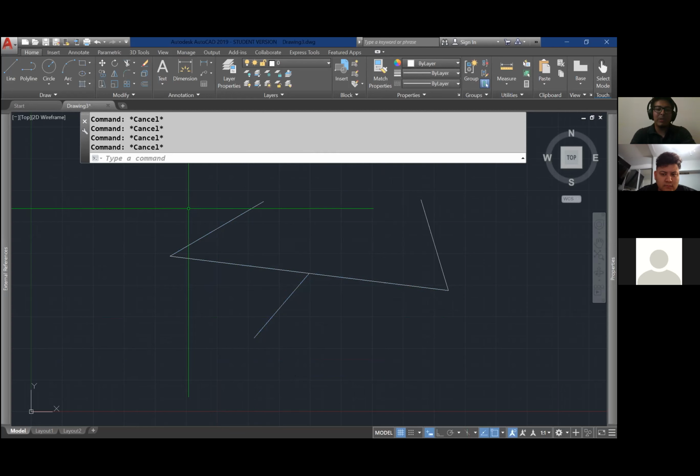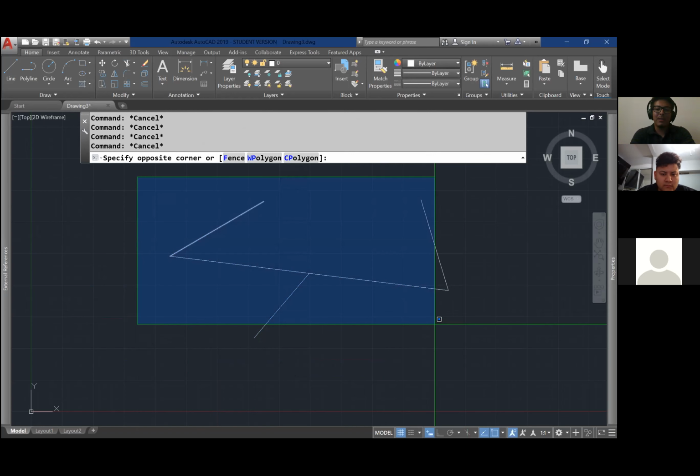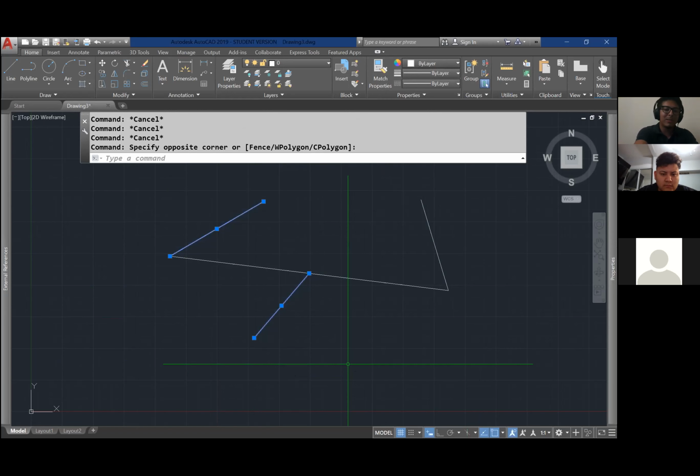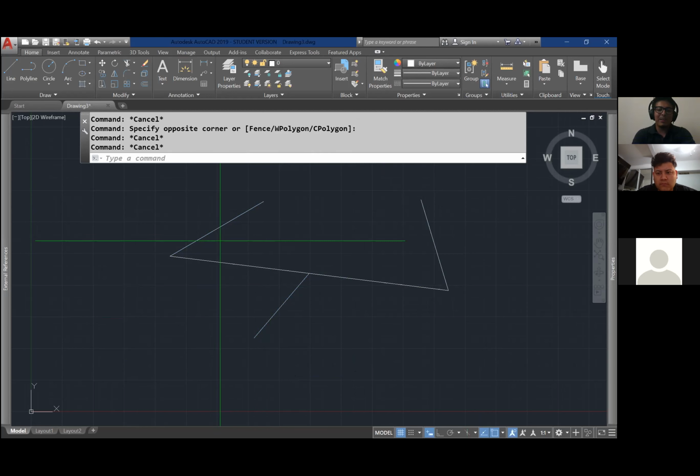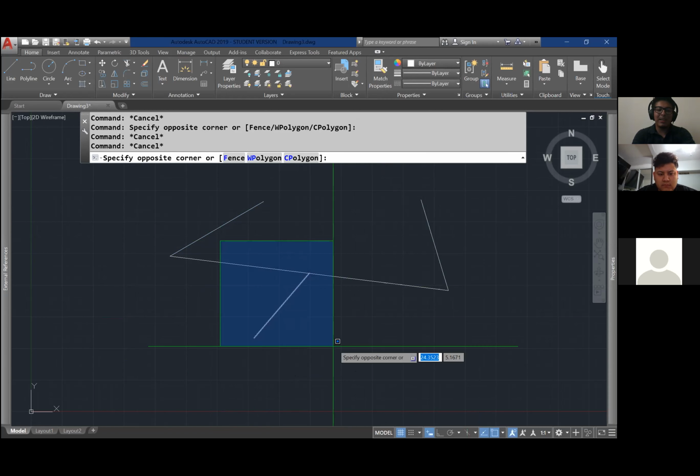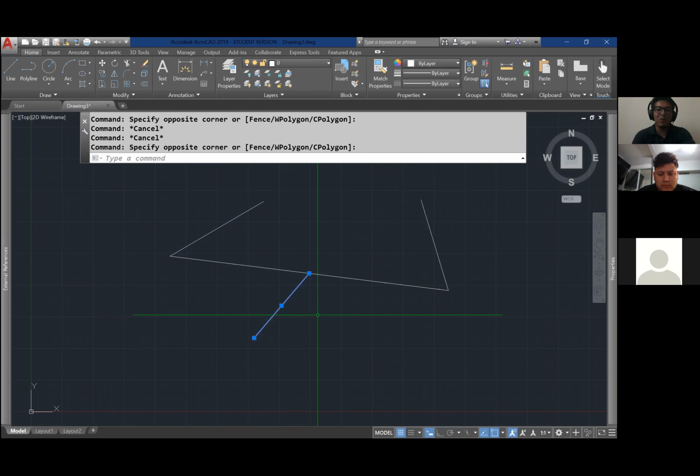Now, similarly, if you click anywhere on your screen and drag towards your right, a blue box will pop up. So blue boxes only select the things that are inside them. Like I just let go of this blue box, you'll see these two lines got selected. It only selects the things that are inside them. So it's really good if you only want this line, and you just get that line because only that line was inside the blue box.